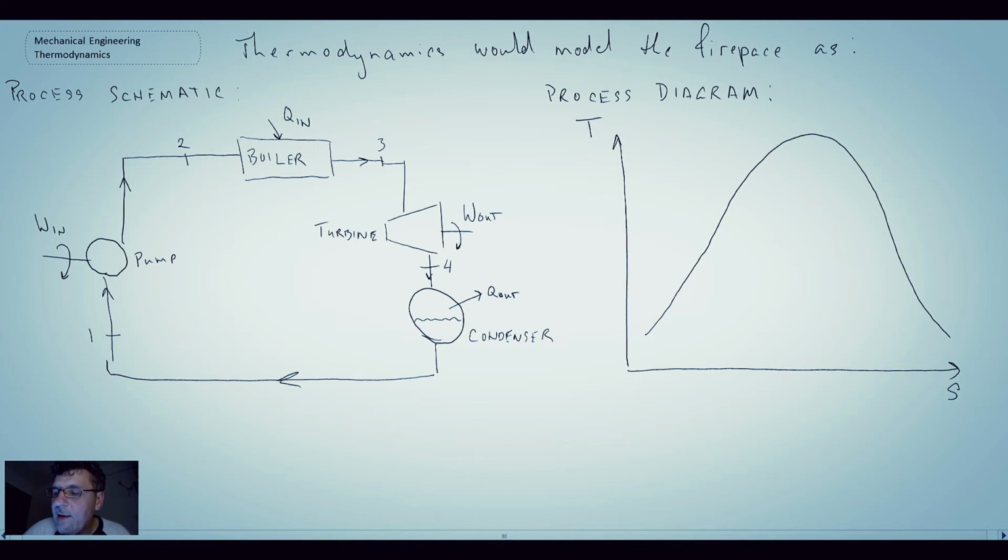And the things to the left here denote compressed fluid. Over to the right would be superheated fluid, and then in the middle here, that's the two-phase region. So we start off in our pump, and we have a liquid, and that is at state 1. And then what happens is we go into the pump and we're pressurizing the liquid, and we go up to another state, that's state 2.